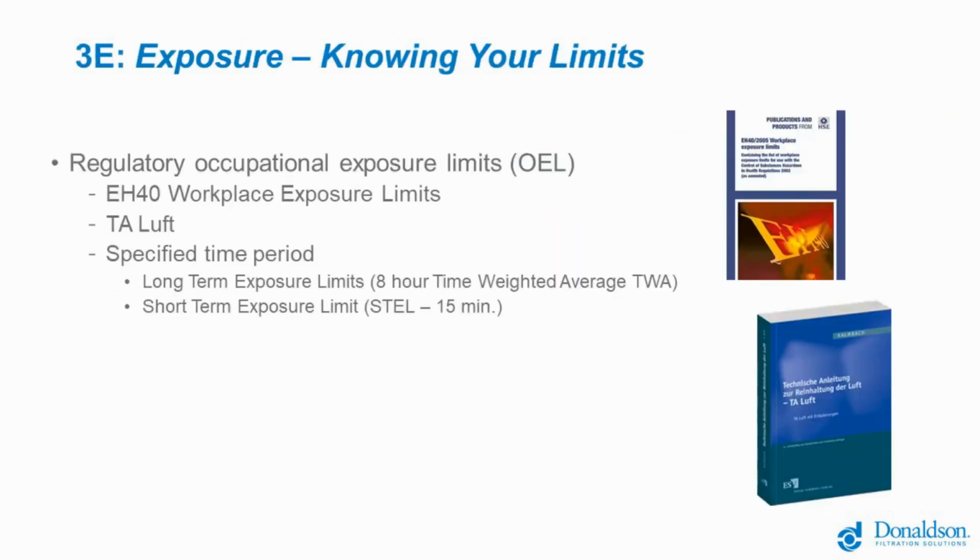There are different regulatory requirements for different parts of the world, and clearly performance of the LEV system needs to satisfy local requirements. A contaminant usually has an official published indicative occupational exposure level, which is based on the severity of the hazard and set to protect the health of workers. Occupational exposure levels is given as a concentration in clean air averaged over a specified period of time, referred to as a time-weighted average. 2 time periods are generally used: long-term exposure limit over an 8-hour period and short-term exposure limit over a 15-minute period.